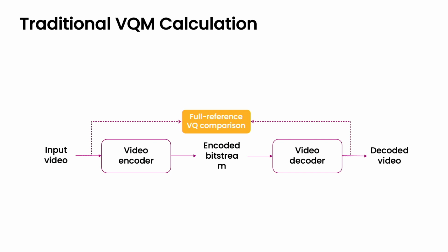So this is something that we see a lot. This is, I guess, the traditional way of calculating VMAF for most quality metrics. I'd say for VOD applications, this is also fine. We've had a talk and some questions out there about applying VMAF, which is typically done on a chunk-by-chunk basis. So first you encode, then you decode, and you calculate the metric. It's perfectly fine if you can afford the delay and the computational power, but it's definitely not the most efficient way.